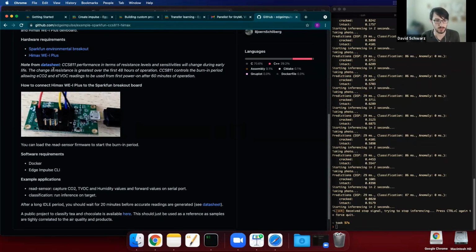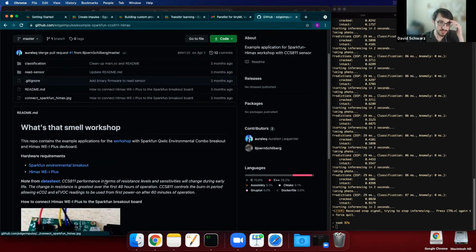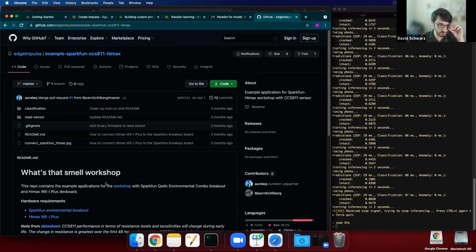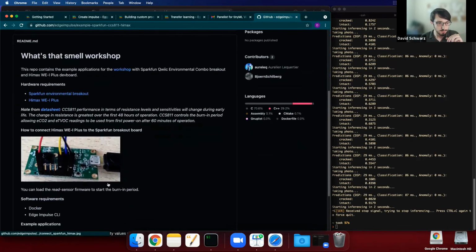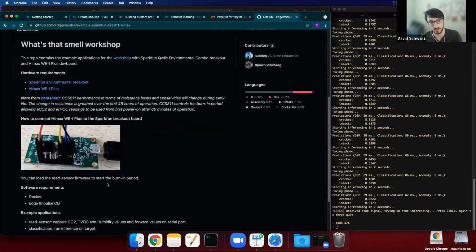And if you're going through our own data forwarder, you can also define how your data is laid out in the format that it's being output from the serial connection, and that also supports multiple sensors. For this example, which is in GitHub and available open source, we were inputting CO2 and humidity data both at once. The only real limitation there is going to be how much data.